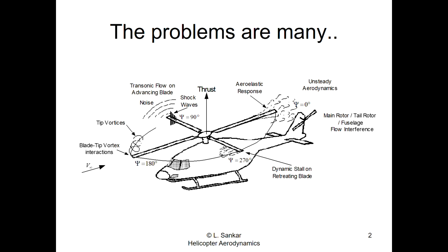It produces extra vibrations caused by the blade-vortex interaction. This abrupt change in the lift up and down also changes the pressure distribution over the airfoil. It propagates away from the rotor, usually in the downward direction and also in the upward direction. The downward direction is where the community lives, so here you hear a noise called blade-vortex interaction noise. You would sometimes hear it when a helicopter is trying to land on top of a building, or when it's descending. This is the blade-vortex interaction noise. This is very, very important.